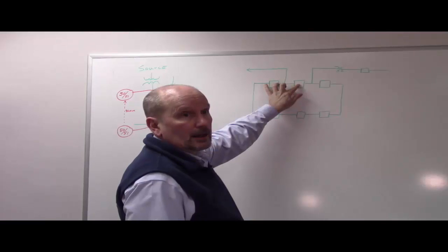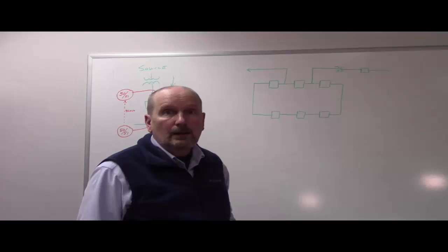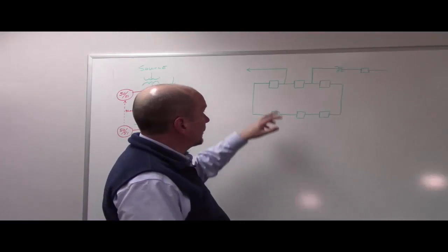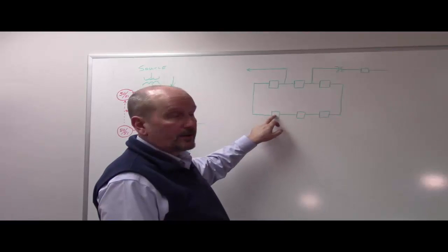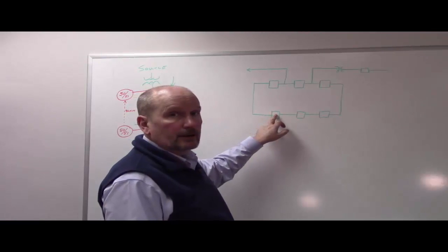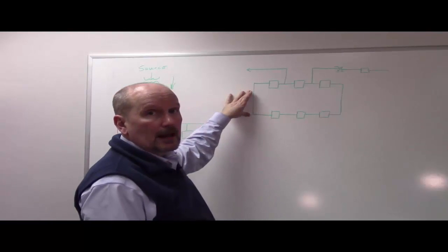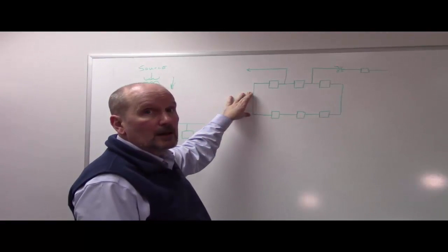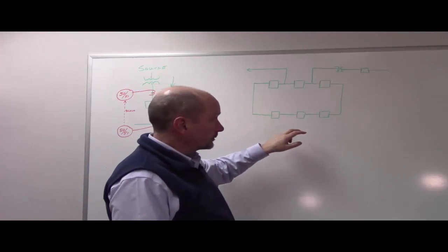breakers. Okay? Well, what happens if this breaker fails to open? We go into breaker failure, and then we have to trip the adjacent breakers, which means you're going to have to de-energize the fault with this breaker down here. Now, this would be a main bus, and if you happen to have something connected to that main bus, it will also be de-energized when you trip this breaker.